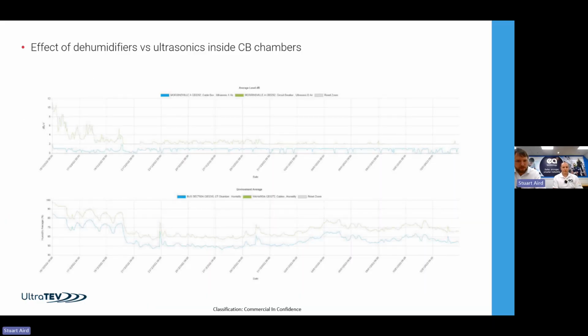With our monitoring system, you can see here that activity was very much related to humidity. So we weren't fixing it by controlling humidity, but in terms of buying time, in terms of slowing the progression, putting dehumidifiers in there and lowering the humidity, still not quite getting to a level we'd like. It's still 60-odd, 65%. We want to be close to the 55 probably. But from the 90, 89 to where you're at, significant drop and a significant drop in the level of activity.